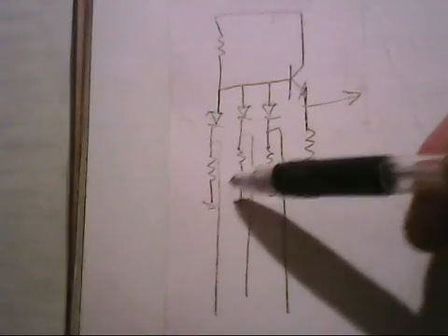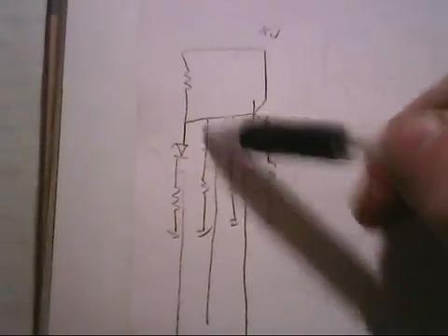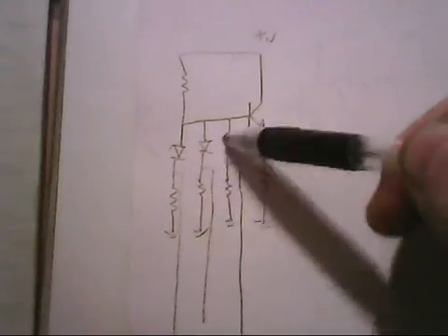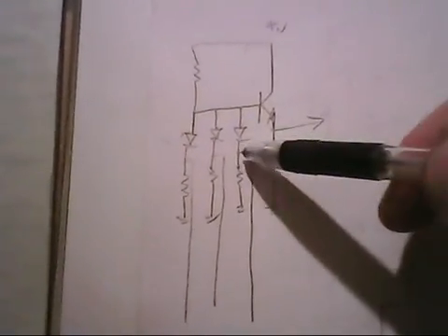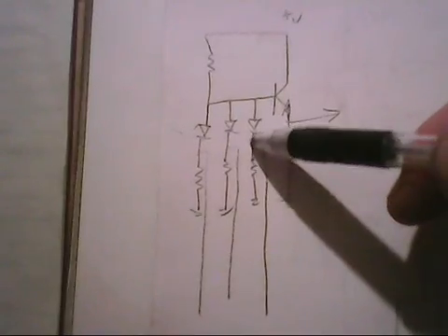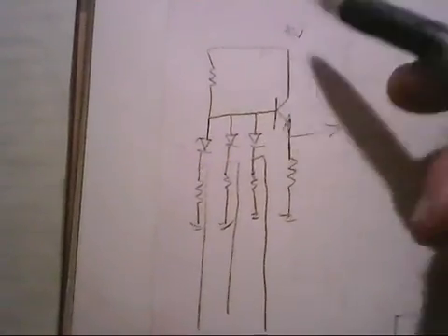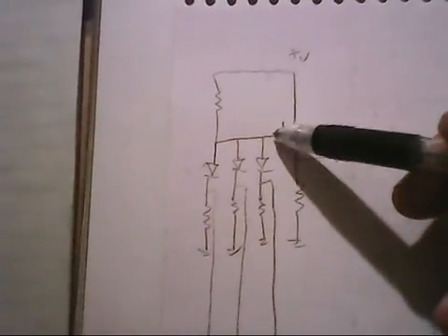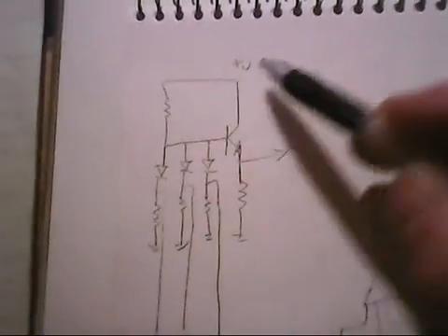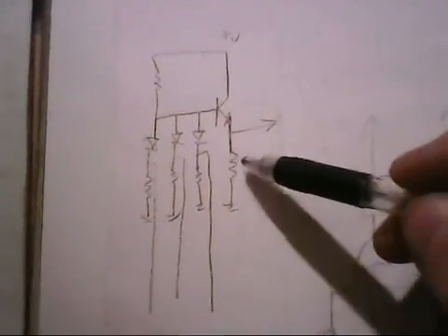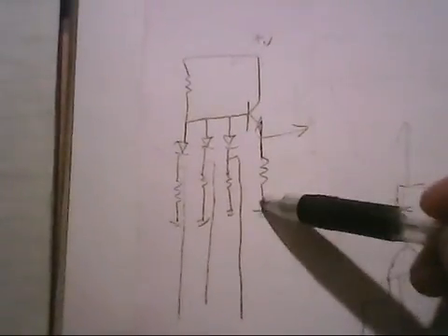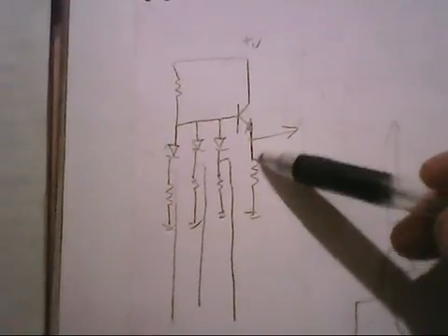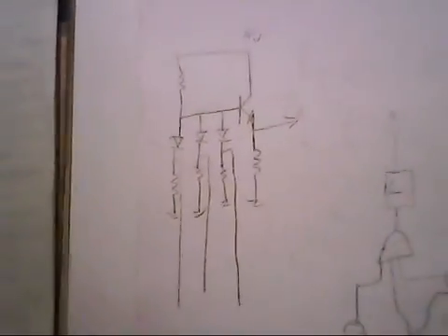That's how I do my AND gates. What happens here is that these diodes are grounded to the base of the transistor through the 2K ohm resistors. When these inputs go positive, it draws current away from the diodes, therefore it draws the negative voltage away from the base of the transistor, causing the base to rise high through its base bias resistor, turning it on, and then we have an output through the collector emitter. And of course this resistor here is to keep a voltage drop across there so that we don't have any erroneous outputs when there are no proper inputs. So that's how I do the AND gates.